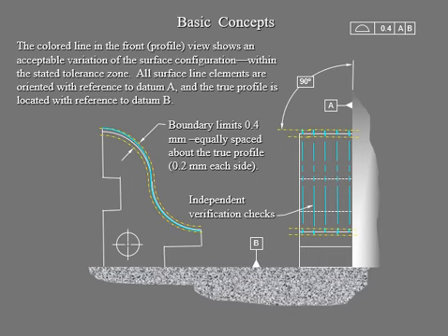Let's go into there, and now we see the little zone for your surface, which is your profile right here, and we have 2 different arcs. The first arc with the first radius, and the second arc with your second radius. You can see this boundary limit is identified in your control frame right there, 0.4. Your datum A is here on this view, and then your datum B right there. We're going to gauge it.